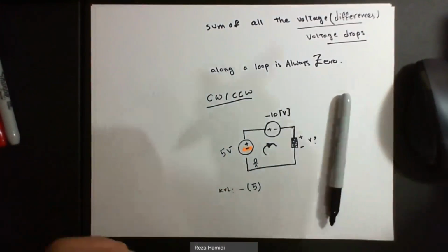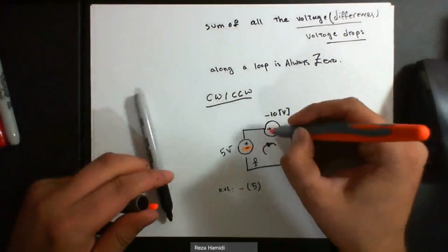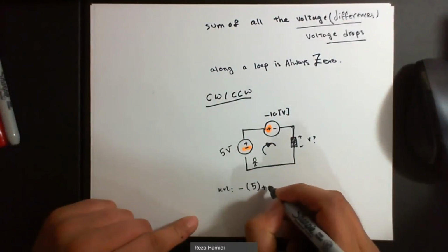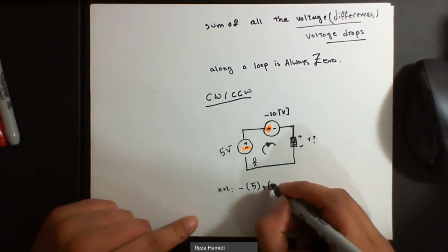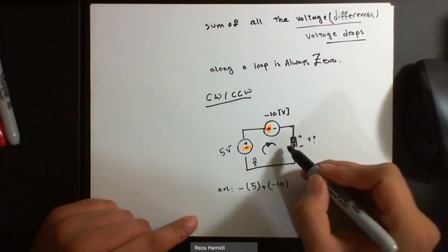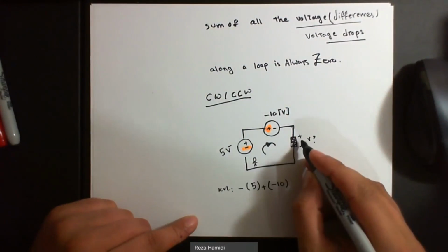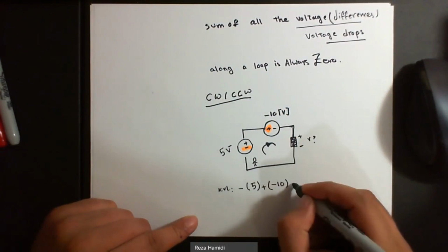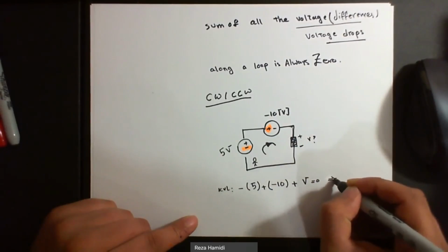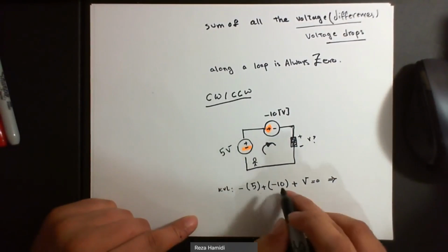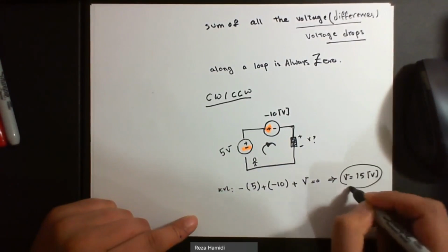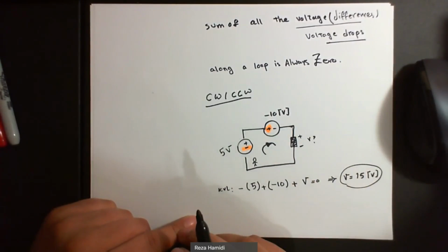But this time, this guy sees the positive head. So it's going to be positive. And how much is the voltage? Minus 10. Then this guy reaches this unknown voltage, but from its positive head. Positive, then unknown V. It's going to be 0. Then, how much is V, you think? Negative 15, then V is going to be 15 volts across this component.